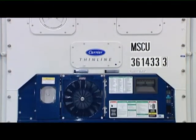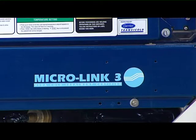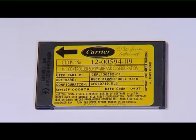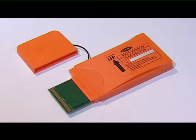Since MSC is also operating the last carrier unit built, called Microlink 3, we'll be forced to supply each vessel with the new software PCM-CIA card. This card will include all different operational software, number 1207 and number 5132, and configuration for all the available unit model numbers, Microlink 2, Microlink 2i and Microlink 3. The PCM-CIA card is compatible to the Microlink 2 and Microlink 2i controller by using an adapter.